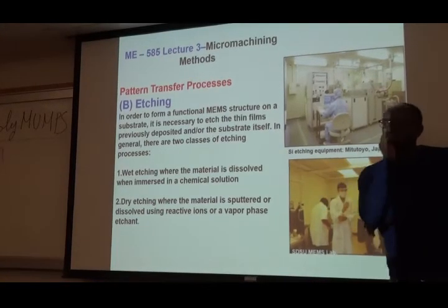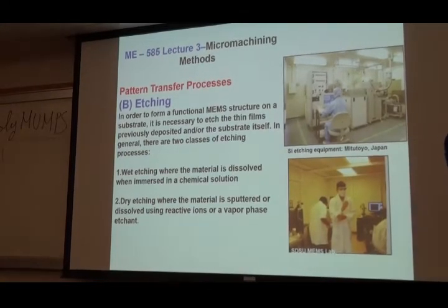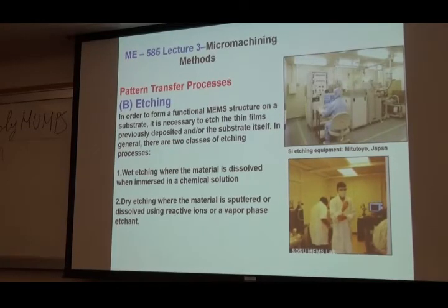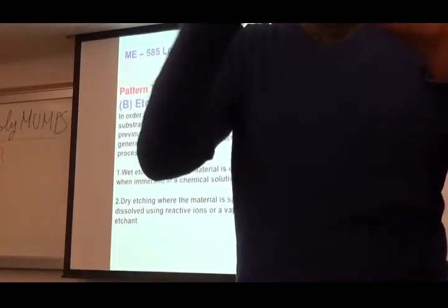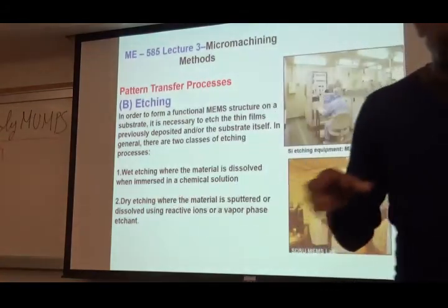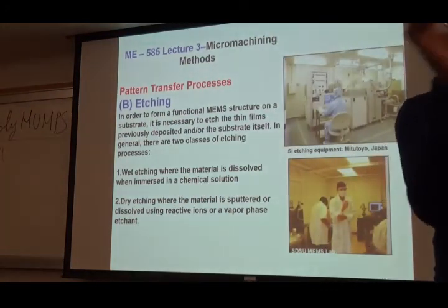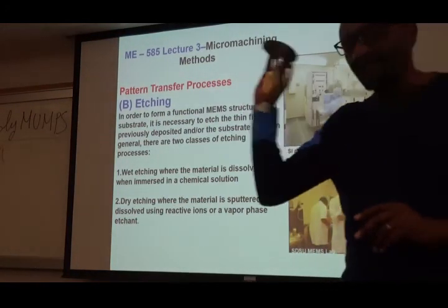Now, wet etching, like I said, involves a chemical. So you have your wafer. It's protected by your photoresist polymer. That's why I was telling you about this story. I put this in a chemical, and then whatever part I don't want gets etched. For example, if it's silicon and I'm covering it with photoresist where I don't want it touched, but wherever I want it touched there is an opening, I want the silicon to be etched.